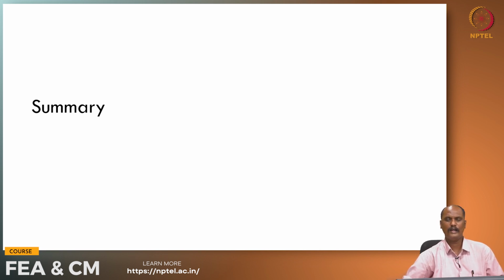What has not been covered is the dynamic aspects of soil behavior. And most importantly, when it comes to creep behavior, there are some other types of soil models wherein the creep coefficient, namely mu, has to be measured and then incorporated. And when it comes to small strain stiffness, we have some other advanced constitutive models which include small strain stiffness also, and that has not been covered in this particular lecture.